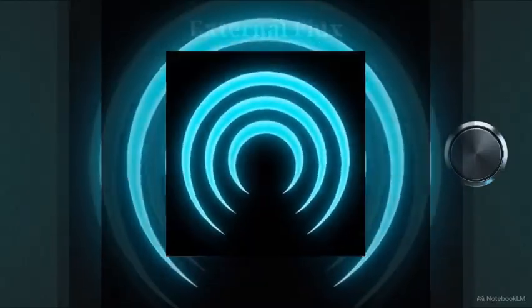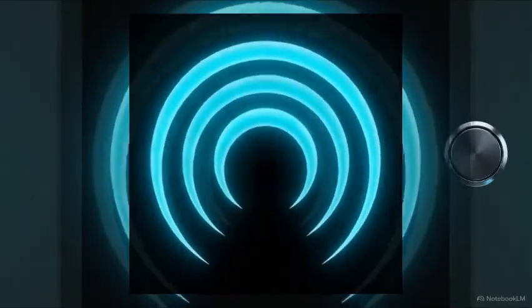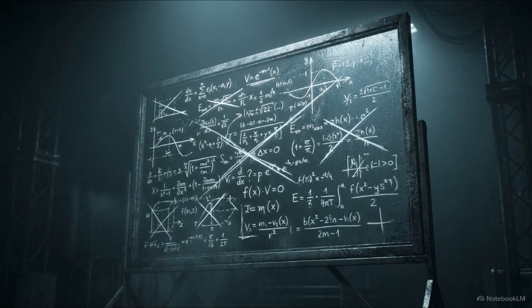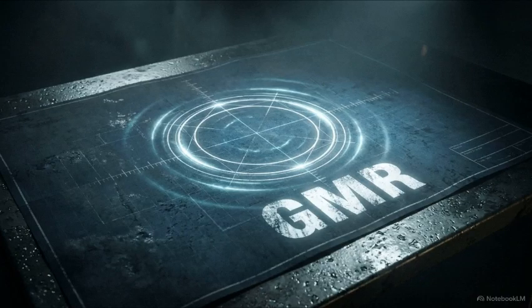Meanwhile, the external flux, the magnetic field radiating outward from the surface of the wire into the surrounding air, varies depending on the distance to any neighboring wires. Running separate mathematical equations for fixed internal flux and variable external flux across thousands of miles of cabling is an agonizingly complex process for grid modeling. To bypass this complexity, electrical engineers created an elegant mathematical cheat code, the geometric mean radius, or GMR.